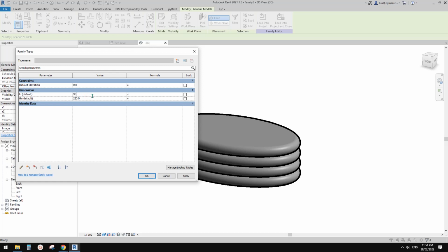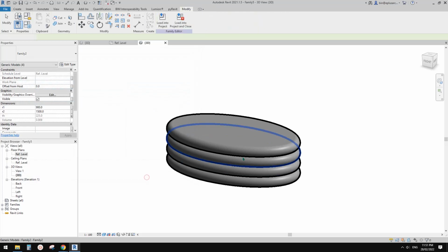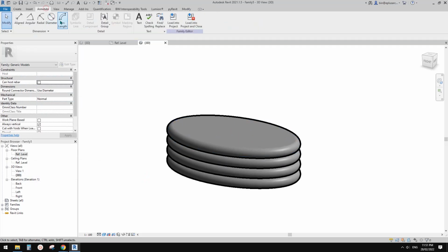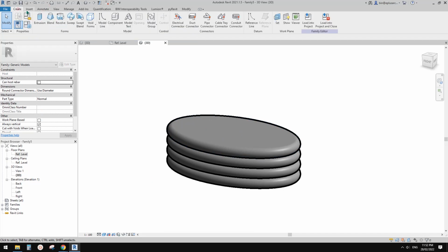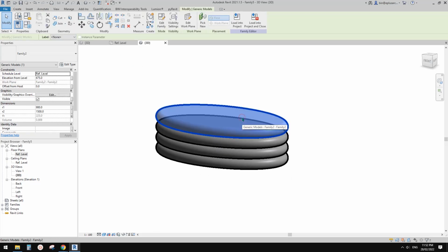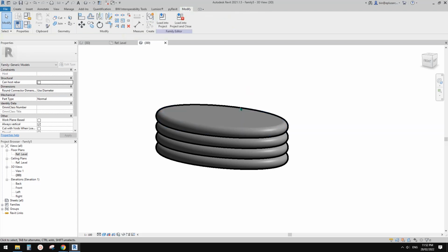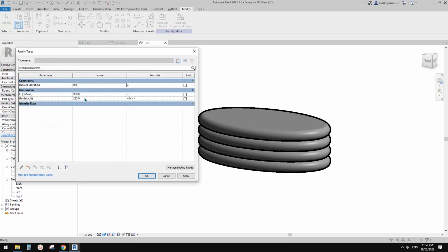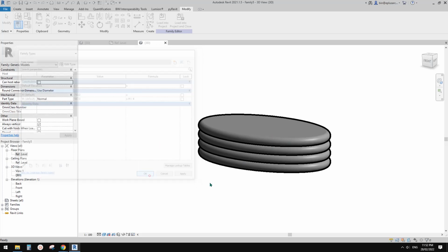So for example, I want for this 900 for now. So we can just go to thickness and use h divided by 4, so depending how many of this we have. So that will be 400. We don't have a spot elevation, but that's fine. That's 900 here. So now if I change this one to 750, all these panels will change accordingly.